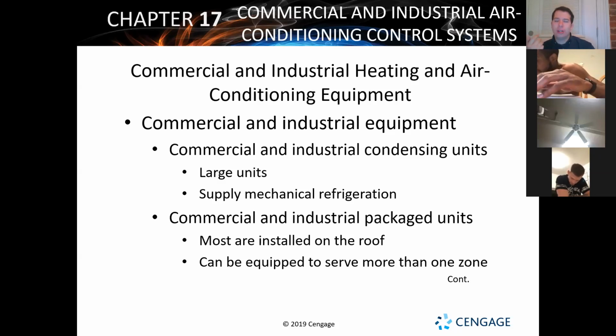it'll have the refrigerant run a shorter distance, quicker cycle, and allow for that cooling and heating process to take place a little bit sooner than we expect. So that's the nice thing about the package units. The split units are not used as much, but you will see them from time to time. For industrial package units, you'll see it where either everything's all together in one place, or there's a short run between the compressor and the condenser, or something like that.